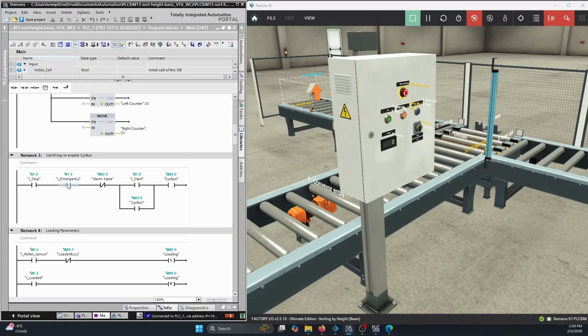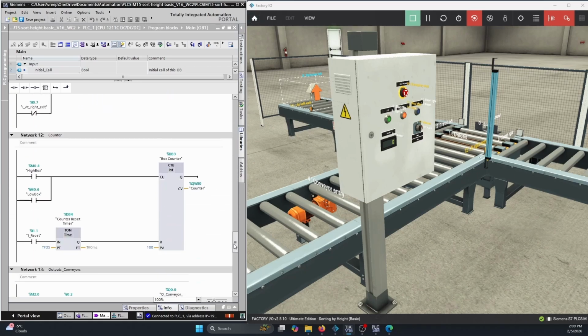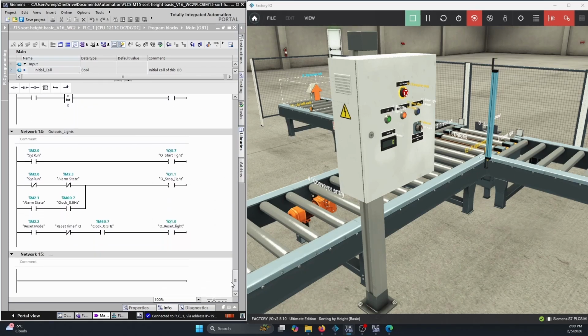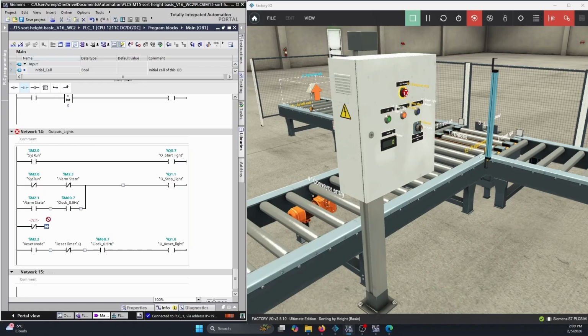So then if we have created the emergency stop to be false, we also want something happening with the lights there. Maybe we can get that red light to flash as well if we're in the e-stop mode. So that would mean that we'd put a parallel rung here and say that when the e-stop is false, it has to be in series with this clock memory bit here.